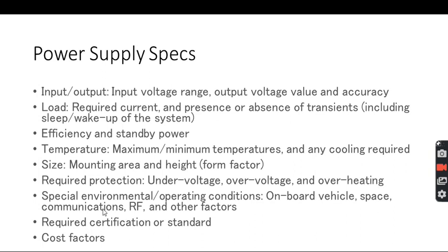And communications, whether it is RF communication, Bluetooth, Zigbee or OFDM. There are multiple things that we'll be using for communication. Which particular communication do you need? 4G, LTE, 5G, all those things will come here. And RF technology also, radio frequency technology, and other factors you have to ask them. If it is used for RF communication, there is a chance of EMI being introduced on the power supply also. So in order to remove that, they'll use filters to avoid EMI from other sources, or they have a particular design for removing the EMI. Like that they can try.